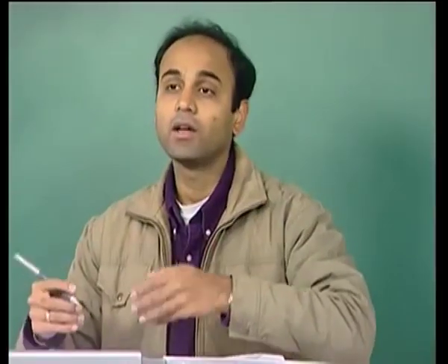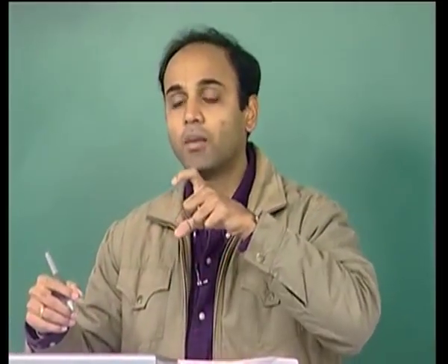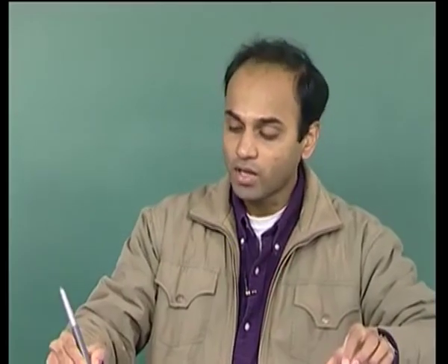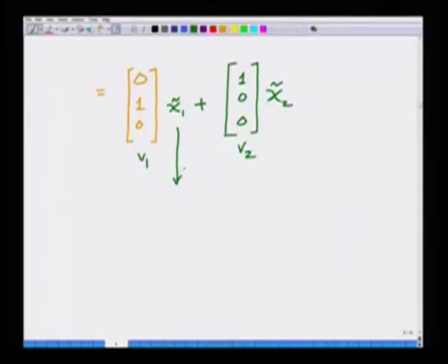Remember, you cannot simply transmit any transmit vector, but you have to pre-code whatever transmit symbols are there with this matrix V, right. That is what results in the decoupling. And now, this is easy. X 1 tilde is nothing but you have to allocate power P 1 to it. So, this is square root of P 1 into B 1, where B 1 is a unit power symbol. This is square root of P 2 into B 2, where B 2 is a unit power symbol.